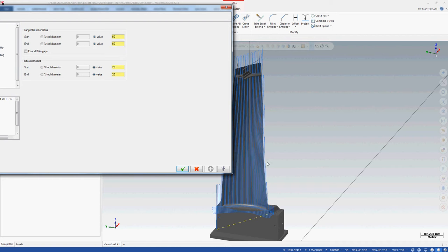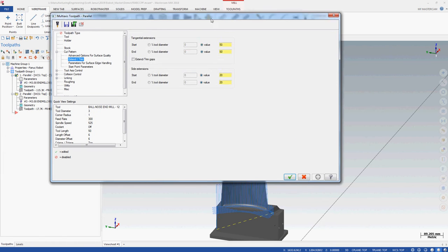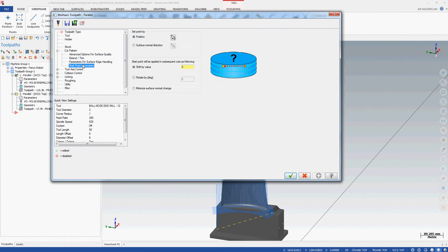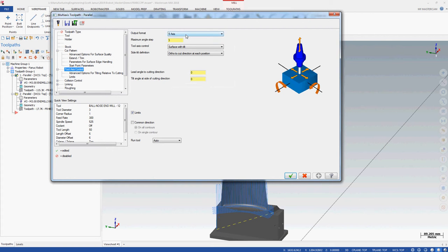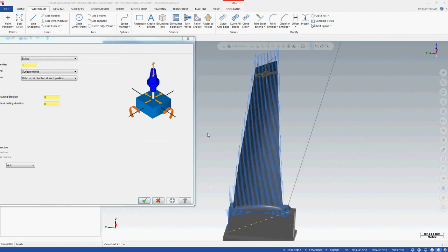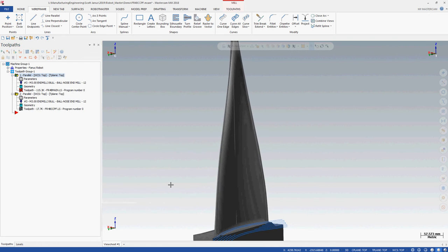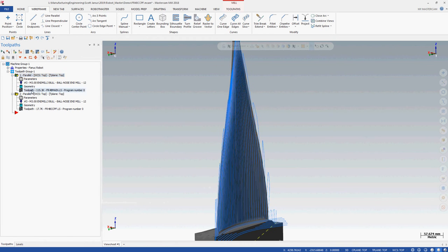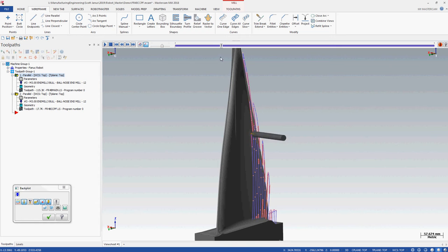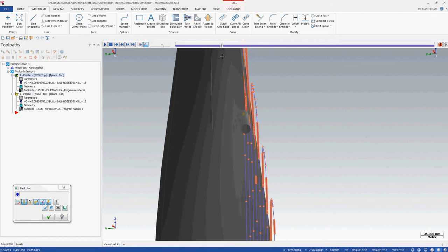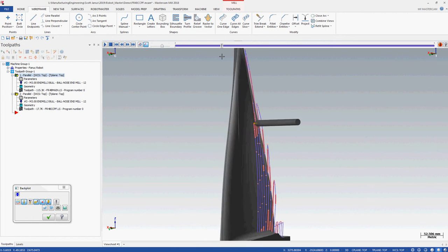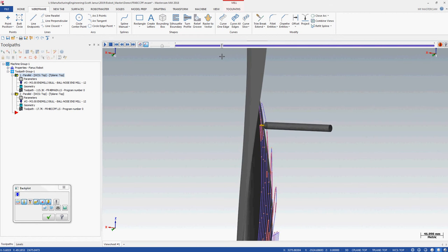In the parameters, I'll show you some basic functionality. All right, so you have your tool, which, keep in mind, this is for machining, so most of it doesn't mean anything, but like your feed rate, start everything off at like 300 millimeters per second, and keep everything in metric. Makes life a lot easier. And that's about all you have to change: your plunge rate, your feed rate, and your retract rate. Keep them all the same. You can play around if you want to, but we usually just modify them at the robot.